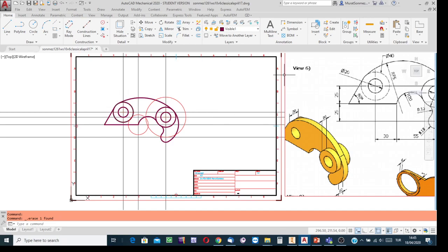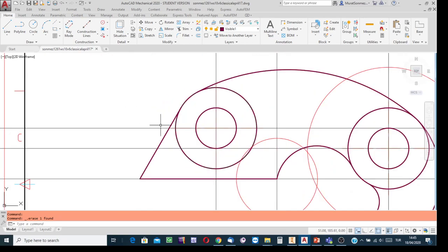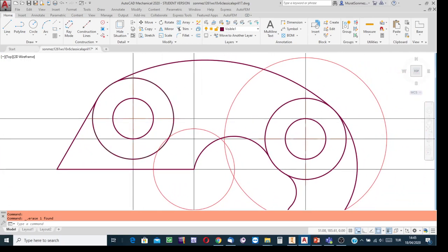Time to apply the trimming process for having the hidden circle over there only, because after creating this tangent line and that tangent circle, I know that from tangent point to the following tangent point, this part is needed along this visible circle, but the rest is to be trimmed. Since the hidden circle and visible circle are coinciding, while trying to trim the visible one, by mistake I may trim the hidden circle.